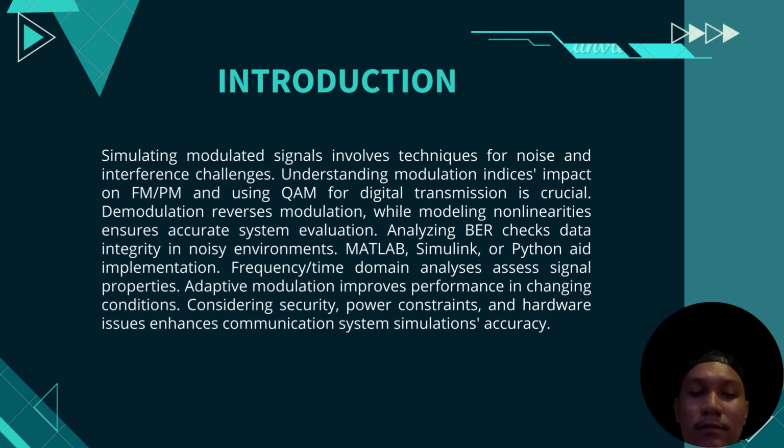Simulating modulated signals involves diverse techniques, considering real-world challenges like noise and interference. Exploring modulation index impact on FM and PM, along with using quadrature amplitude modulation for advanced digital transmission. Demodulation reverses the modulation process, and modeling non-linearities is essential for accurate system evaluation.